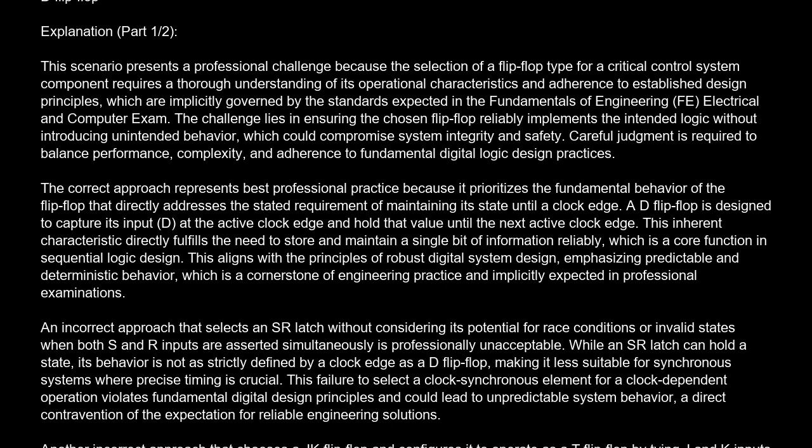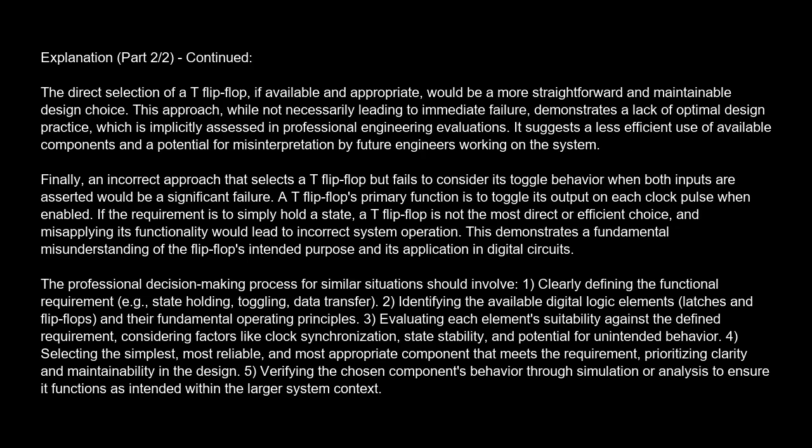Another incorrect approach that chooses a JK flip-flop and configures it to operate as a T flip-flop by tying J and K inputs together, while functionally possible, introduces unnecessary complexity and potential for confusion in documentation and maintenance. The direct selection of a T flip-flop, if available and appropriate, would be a more straightforward and maintainable design choice. This approach, while not necessarily leading to immediate failure, demonstrates a lack of optimal design practice, which is implicitly assessed in professional engineering evaluations. It suggests a less efficient use of available components and a potential for misinterpretation by future engineers working on the system.